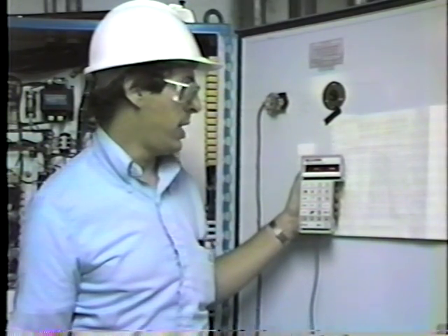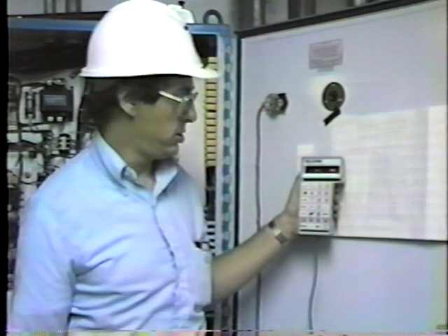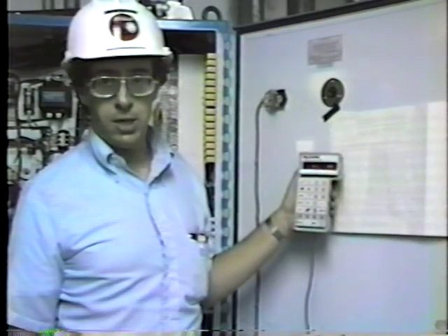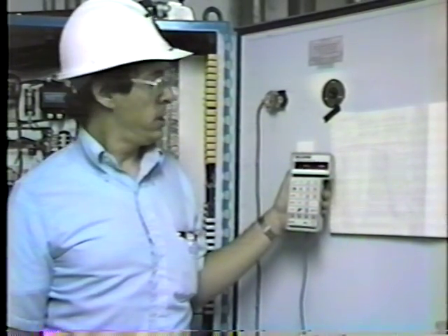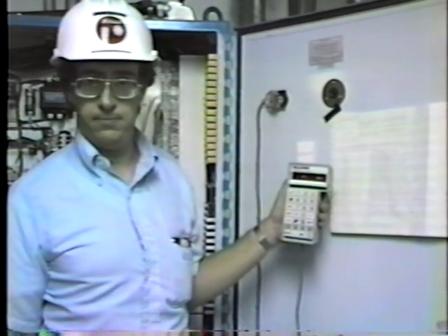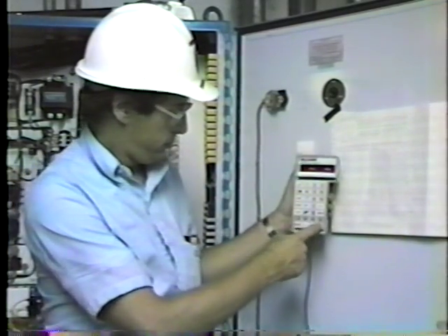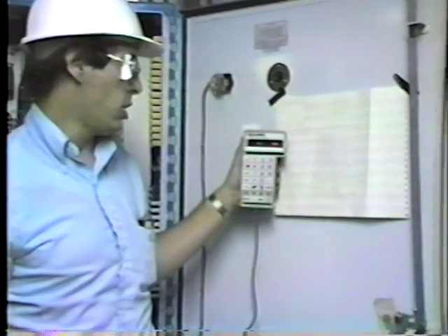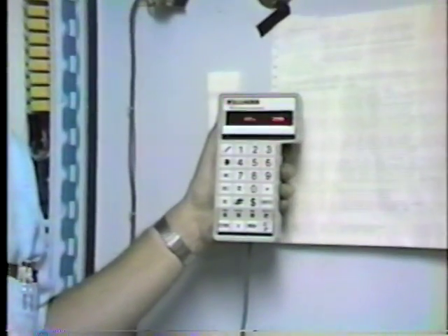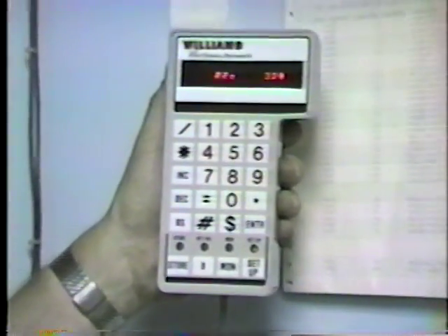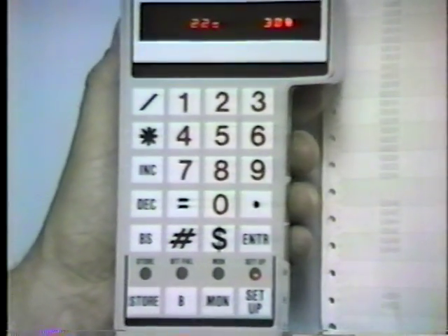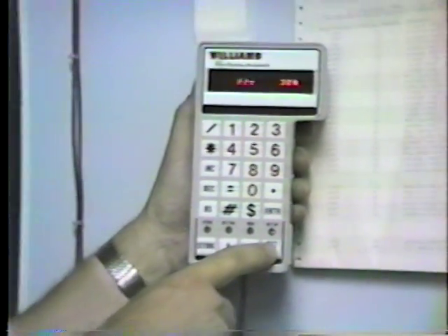Number 21 is the panel alarm timeout value in seconds. This is the time, if you push the DP alarm reset on the local panel out by the pulverizer, that you have to clear up a problem before the alarm will repeat. All right. 22 is the exhaust fan startup delay set to 30 seconds. This could be reduced if you want to, because apparently your fans are across the line, and it could start in maybe as little as 5 seconds. Allows the program to continue.